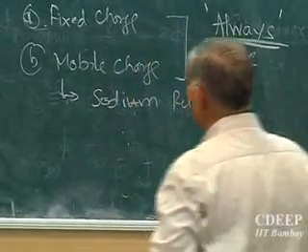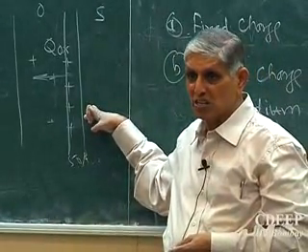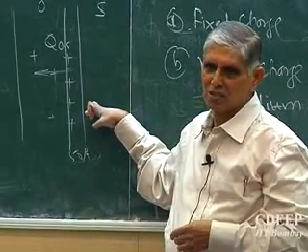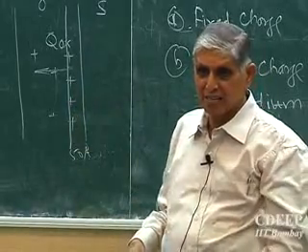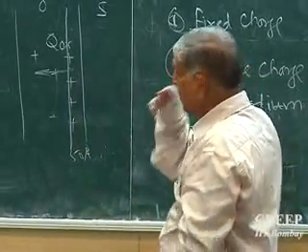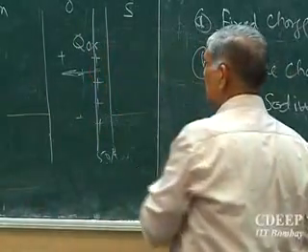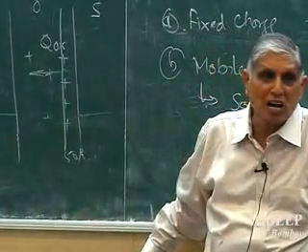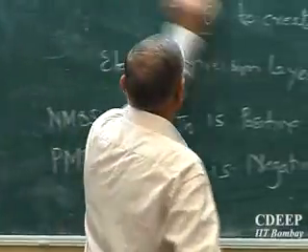So because of that, I will get positive charges very close to the interface, which is within 50 angstroms, at best 100 angstroms. Is that correct? This positive charge doesn't move. Is that correct? Now let's look at the semiconductor. I have not biased it anywhere, Fermi levels are wherever they are. However, as soon as you have a positive charge in the oxide, by Gauss's law, something else is now happening.